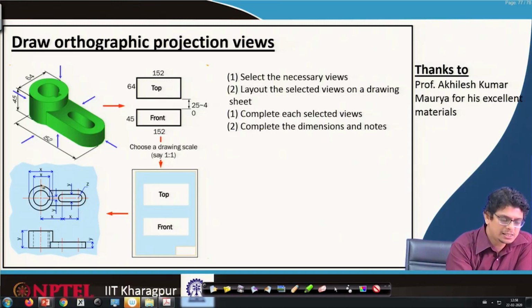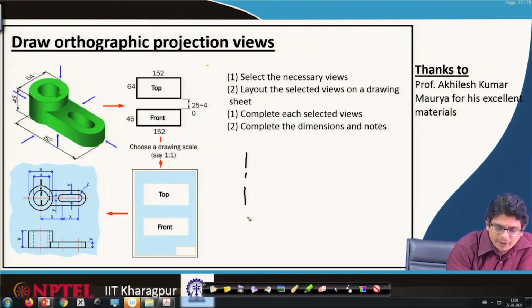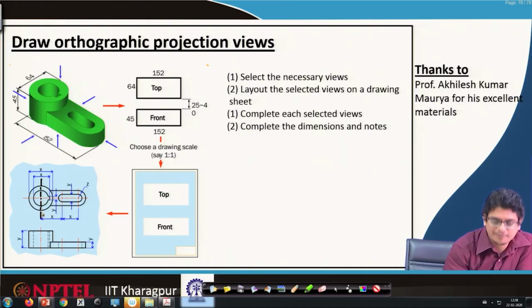These are two circles having a radius, the axis is passing in that way, the axis is passing in that way. So, we show it by a dash dot kind of line, a big dash followed by a small dash, again big dash, small dash. This is the way we represent an axis. Here that big dash, small, again big one, small, big one, small and big one.